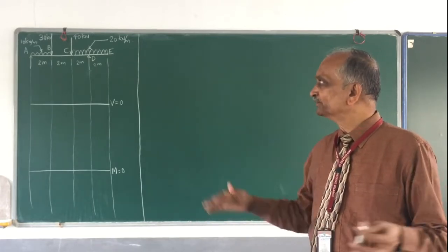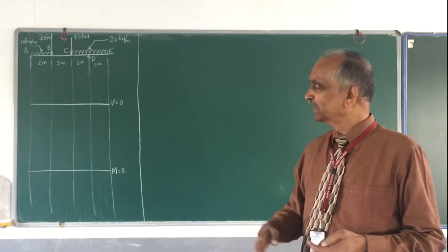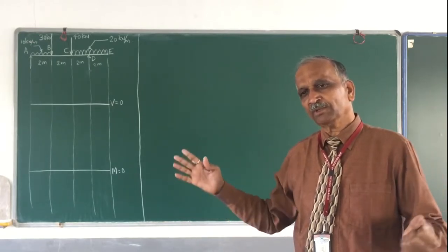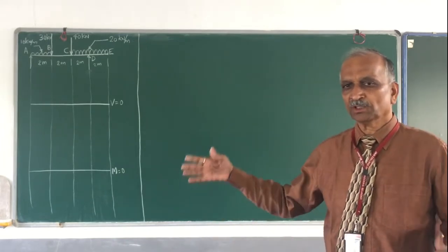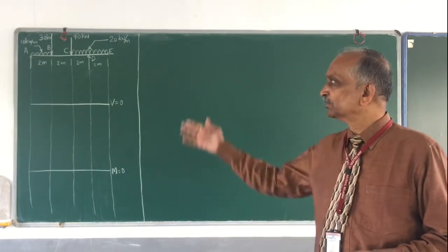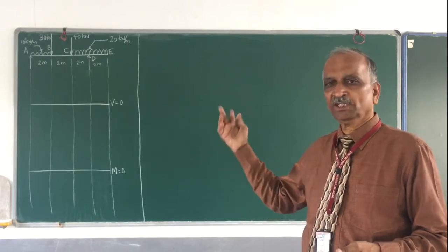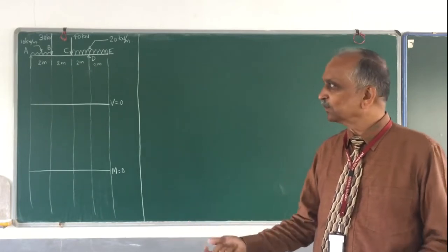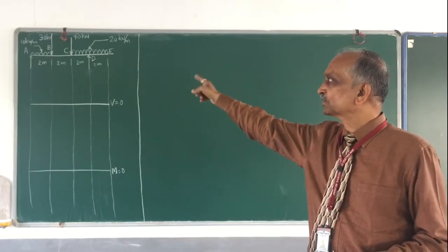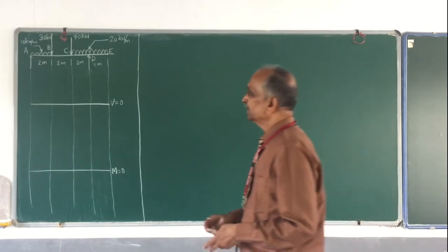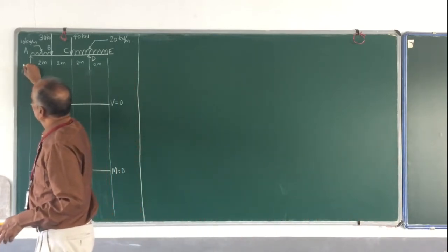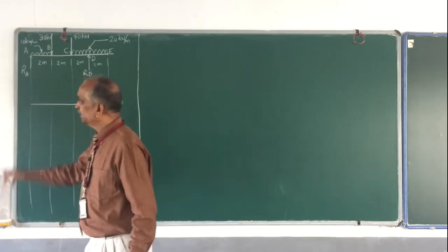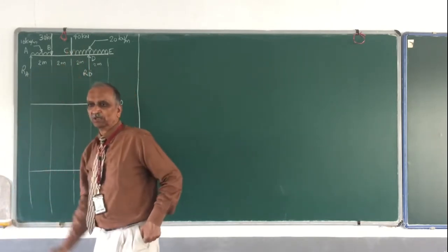Okay, you may wonder there are no supports, so it is not that. Carefully observe, the supports have been replaced by the reactions whatever they offer. So one support is at A, the other support is at D, and those supports probably are roller supports. That is why you have only vertical force at A and D, and I shall name them, say this is RA and say this is RD. So A and D are the supports that you have.